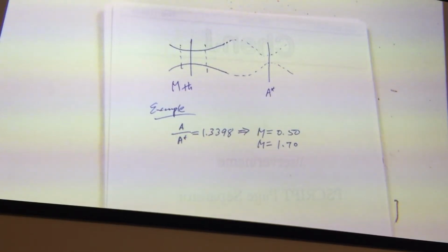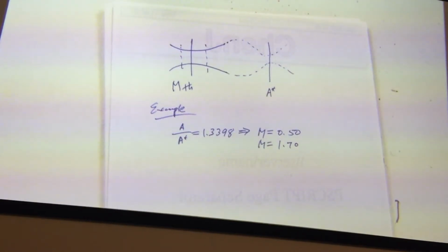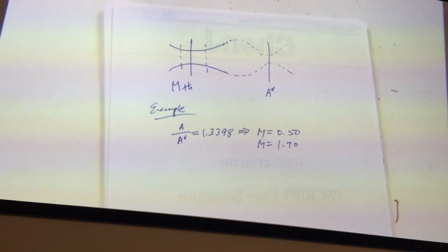You really want to decelerate the flow because in a supersonic inlet, with decrease in area, the velocity, the Mach number will decrease. And you want to design it in such a way that the Mach number at the throat is 1, and then downstream of it becomes subsonic. Right? And then the subsonic air will go into your combustor. And because it's subsonic, there will be no shock wave. Right? If you allow the supersonic air to go directly into your combustor, there will be a shock wave. And if there's a shock wave, it's not isentropic, the stagnation or total pressure will decrease.